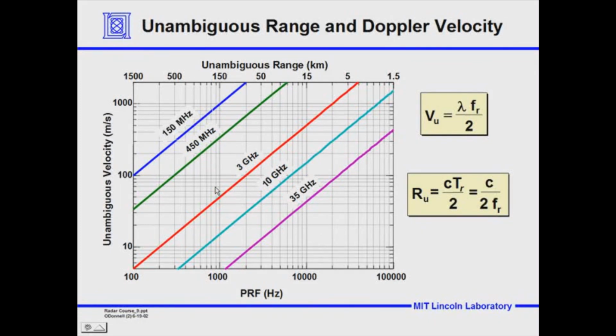Okay? And as I alluded to earlier, for each beam width, 2 sets of PRFs are sent out, and I'm going to show you later how, with 2 sets of different PRFs, varying by 10 or 15%, you can unravel the ambiguity in Doppler. We'll show how we do that a little later.